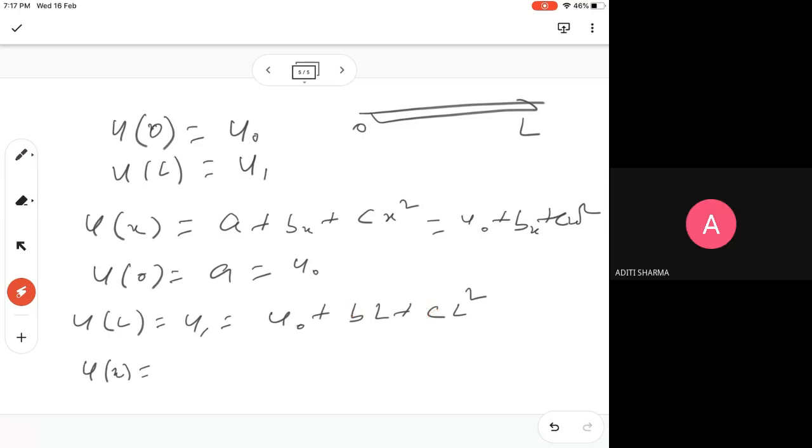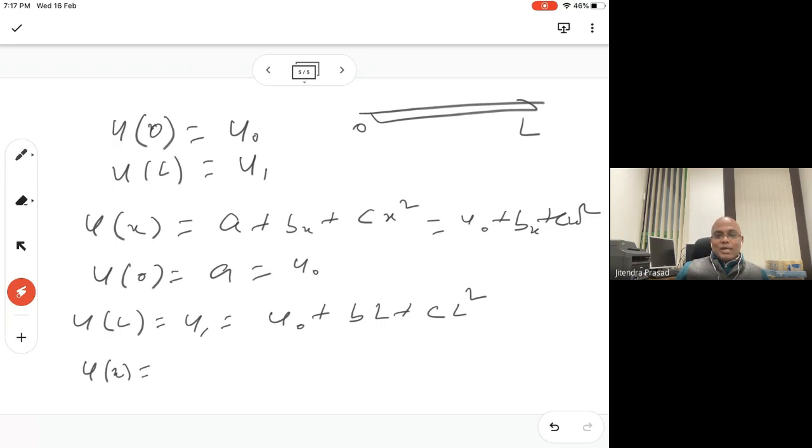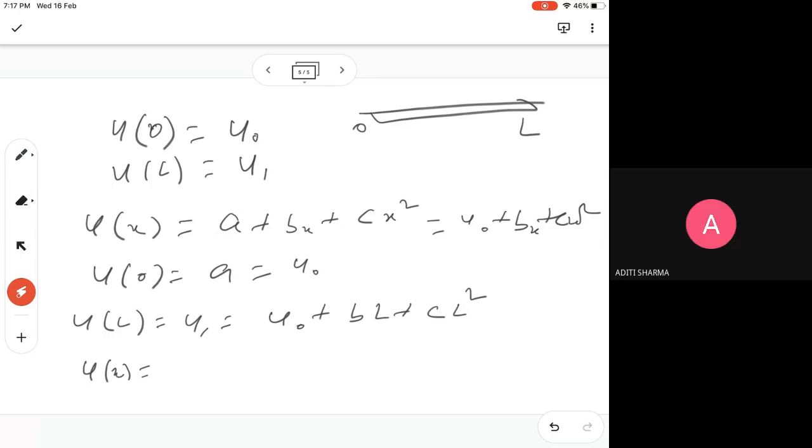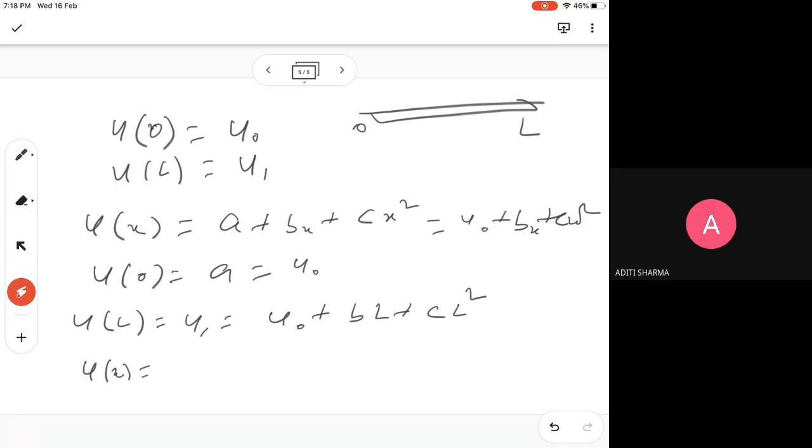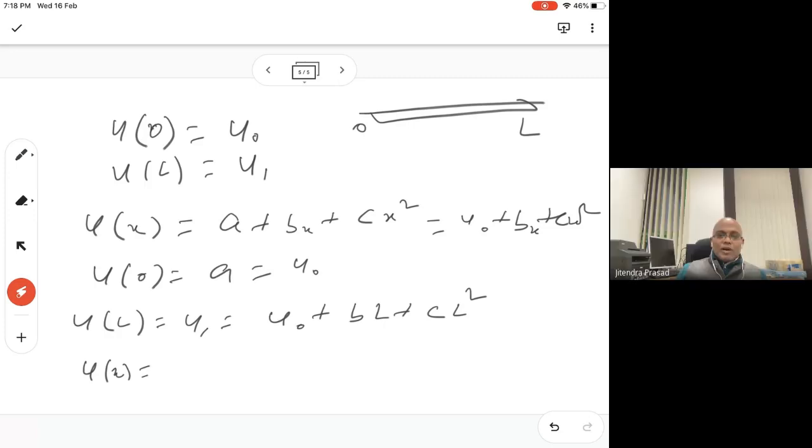Yeah, but in that case the boundary conditions are different. When you apply the Ritz method, your trial function has to satisfy the essential boundary condition to begin with. Otherwise, you will get something else. So the correct method is where we satisfy both conditions first. But what if it is satisfied later on also, but the result is different? It's wrong. The essential boundary condition has to be satisfied to begin with.